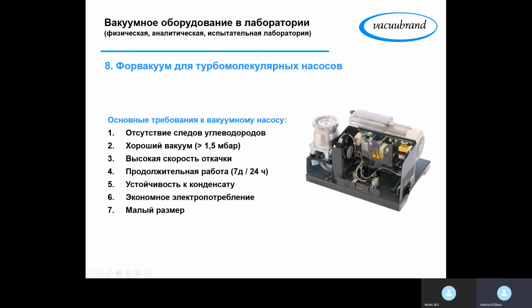Why? Because for different types of pumps, but let's say for the turbomolecular pumps, we can switch it on, but due to the high amount of gas, not always air, but any kind of gas that it has to pump, the turbine will heat up very quickly because the throughput of the pump is very, very high due to the performance, the rotating speed, and so on.